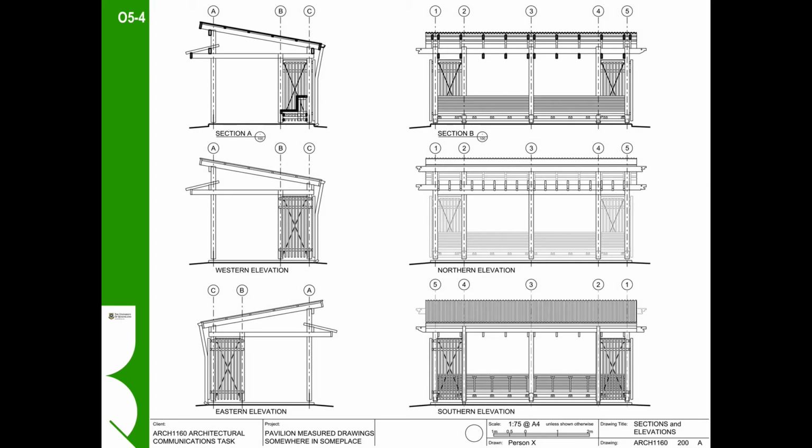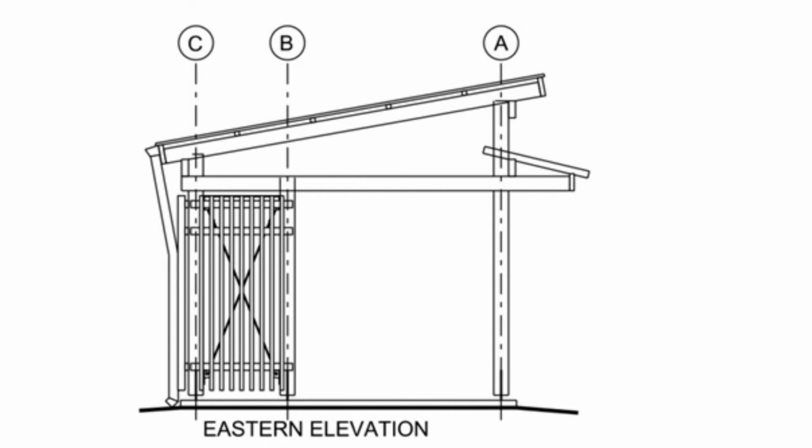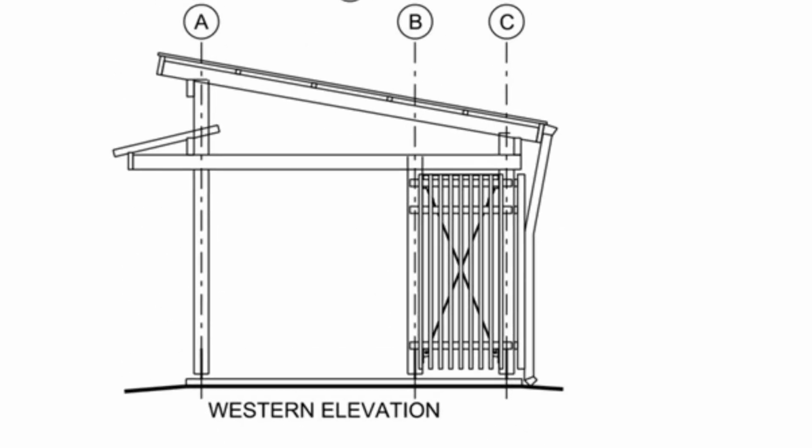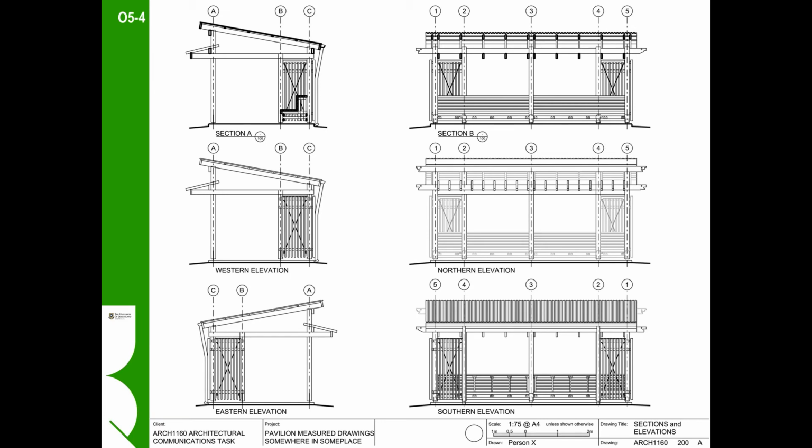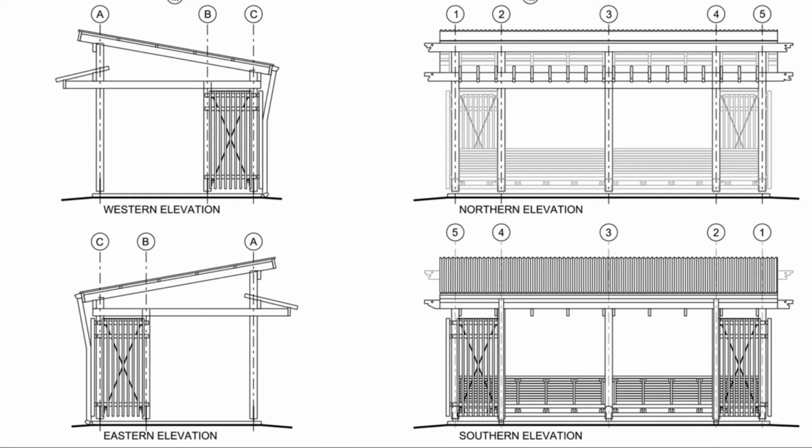Note that we have added the other missing short elevation. It is a simple reflection of the previously drawn short elevation, so it doesn't take us too long to produce. For the workshop, note that we only need to produce 2 sections and 2 elevations. Note that when we label the grids on the sections and elevations, they are orientated correctly to the plan.